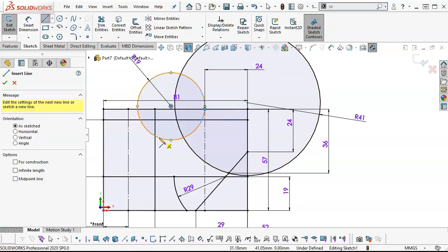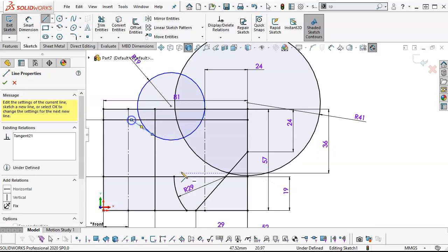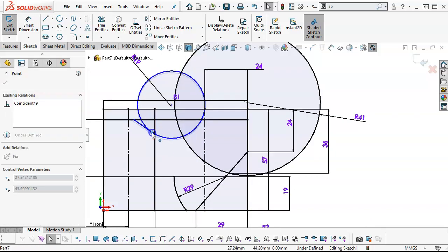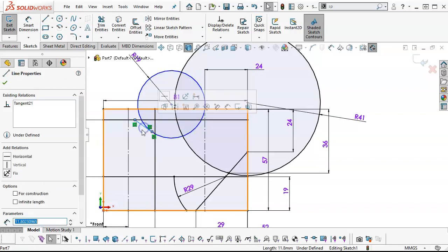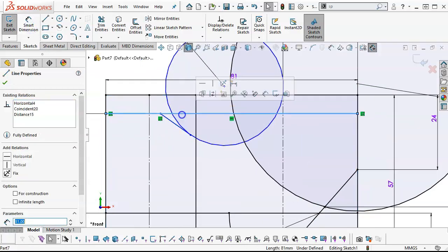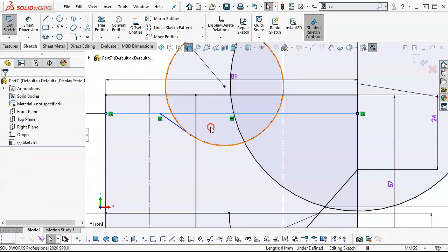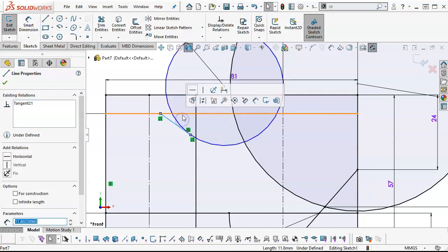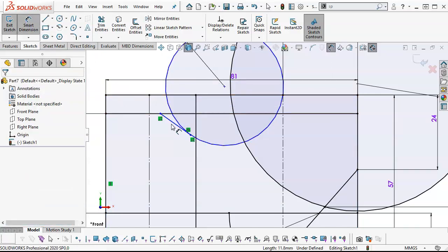We have a 10-degree arc. So bring that, make sure it's coincident, and then it's tangent. It doesn't move strange, and if I highlight the line, I see my tangency and my coincidence. Need to set our 10-degree angle. Oops, helps to be in the dimension tool. Okay, getting a little button happy.